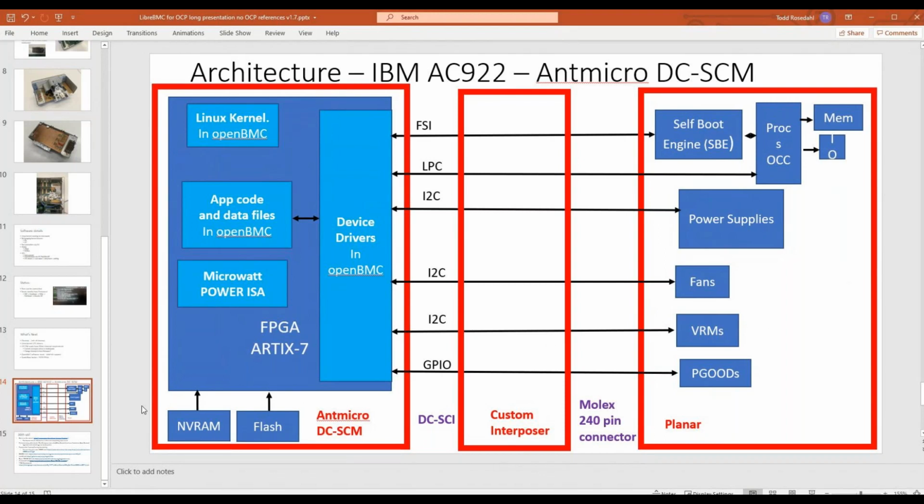And the goal is always to maintain it as a soft IP for the core running the OpenBMC, or do you also accept solutions with hardened cores? Hardened core being you buy off-the-shelf silicon. Well, there are certain FPGA SoCs that already have hardened cores in them. I think Xilinx also supported PowerPC at some point in this kind of configuration, in the Virtex Pro series in the past. But that's just an example of an FPGA SoC that has a hardened core paired with FPGA fabric. Is the hardened core open and completely inspectable, or is it just no? No. So then no, that would not be.